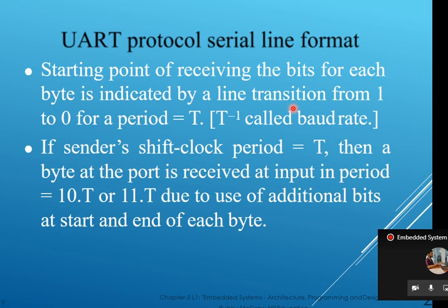And if you see, I told that if suppose the 8-bit data is transferred at the time period of t, in the receiver it will take 10t or 11t. So what is 10t representing? Actually, 8t is the duration used for the 8-bit data, and additionally the 2 bits of start and stop bit, and additionally the parity bit. If I include it, it means totally 11t duration I require.